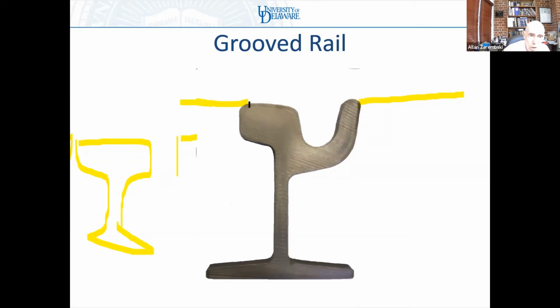You tend to use the groove rail where there's a lot of pedestrian and other traffic on top, so you don't want to leave a gap. If you're using a concrete slab, such as an underground metro, people don't walk down there, and you also have a third rail, so you don't want to electrify them. As a result, you can live with a bit of a gap.